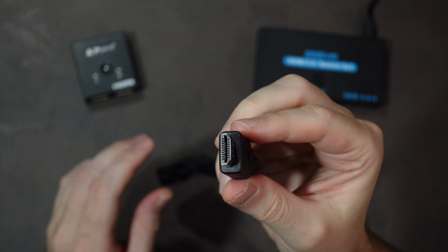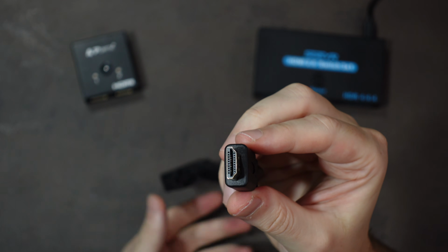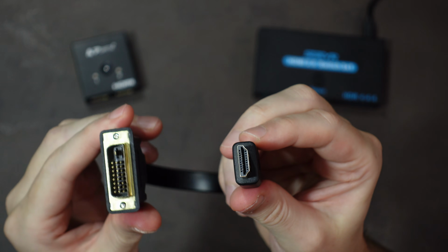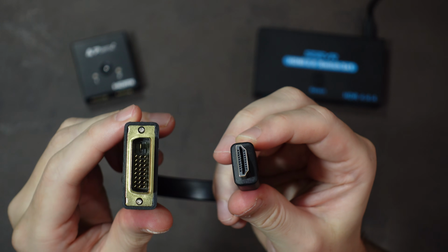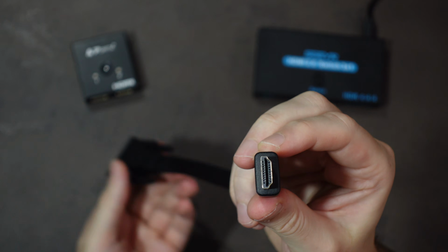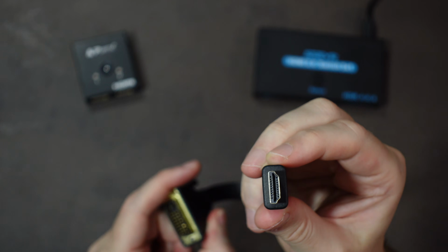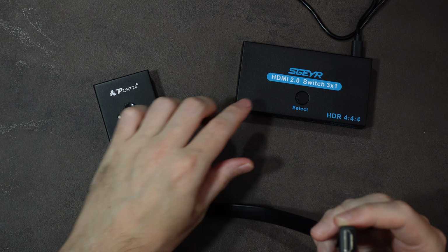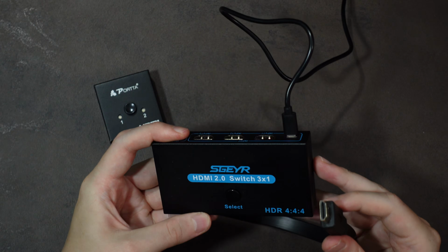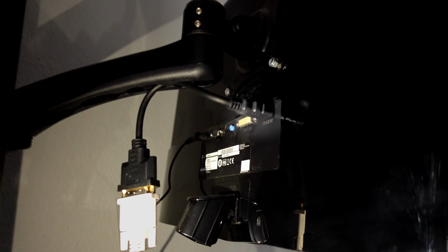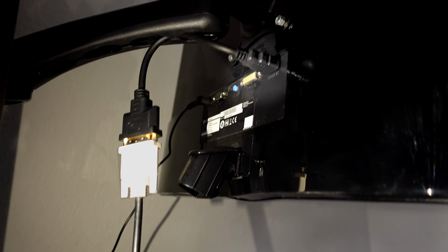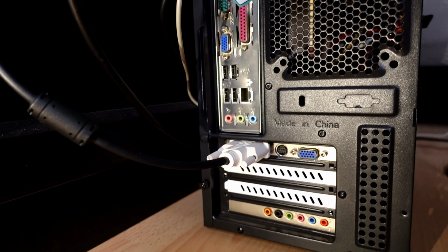It's a similar story with HDMI, where you have to distinguish between the signal and the connector itself, since other signals such as digital DVI can also be sent via the HDMI connection, which makes sense as HDMI basically emerged from DVI. This makes HDMI splitters and switches a much cheaper alternative to DVI ones, if you can find these at all. However, if you send a DVI output of a graphics card to an HDMI input of a monitor, then it depends on the monitor whether or not the image can actually be displayed.